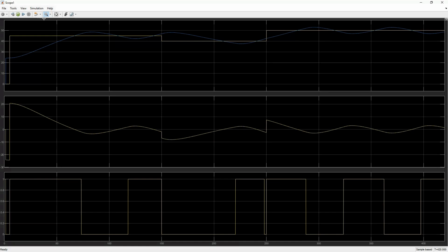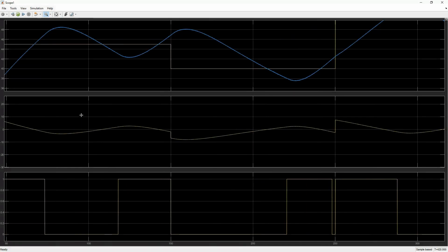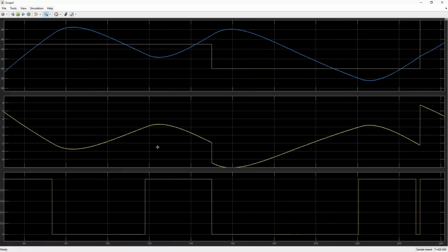So you can think about a 2-degree deadband window around both the error and the control signal. That's why we are not getting any of these problems, because this middle chart is looking at the error, and you can see that the deadband is up here at +2 and -2. So you can see that the noise in the error signal is not enough to bump you outside of that range.